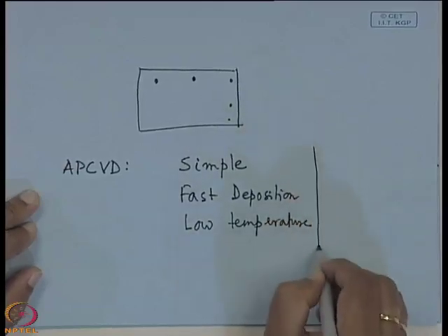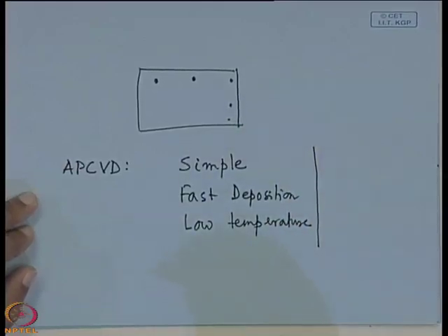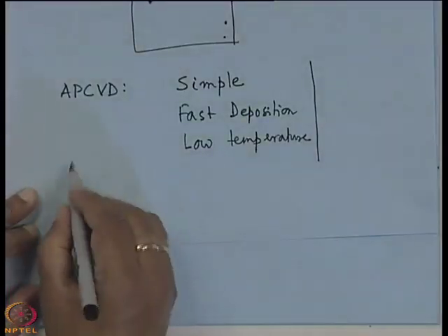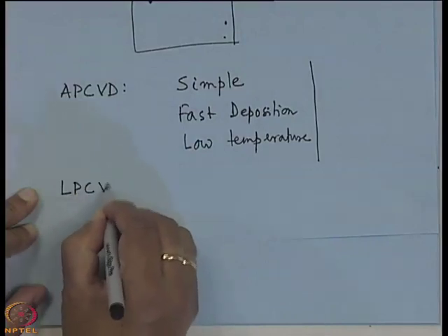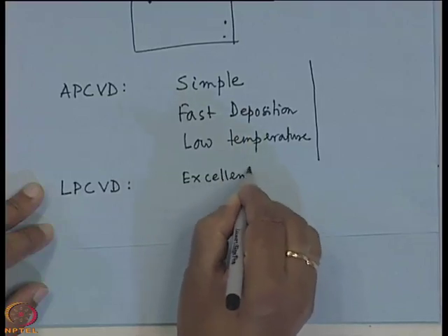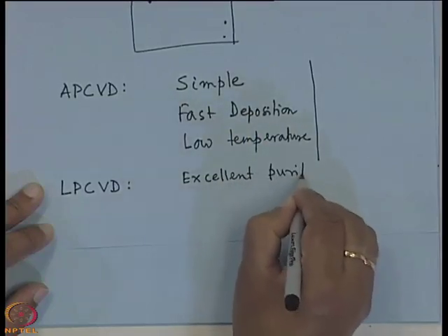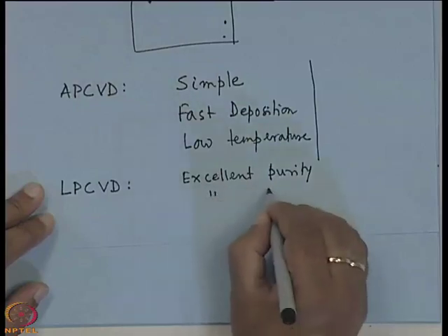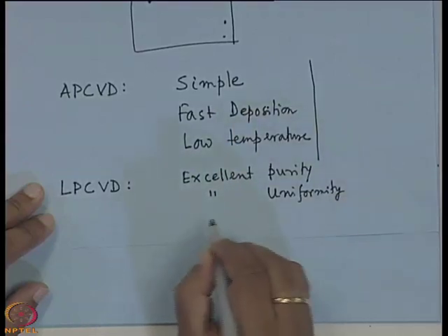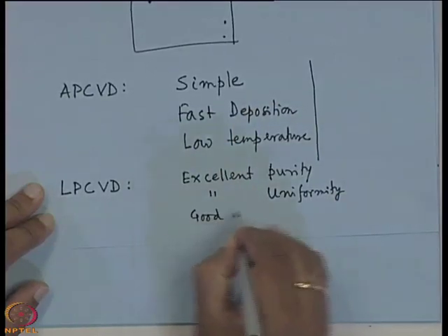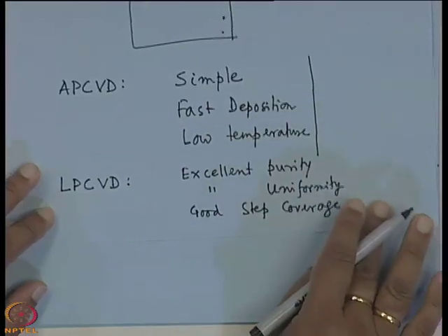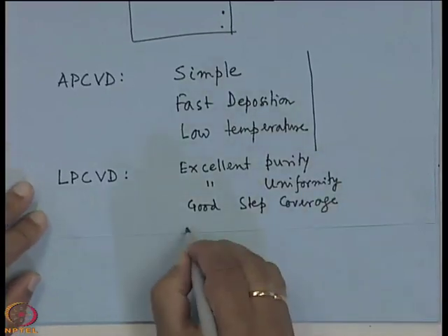So, this is the advantage of APCVD. Now, if you go for LPCVD: excellent purity, excellent uniformity, good step coverage, and large wafer capacity.